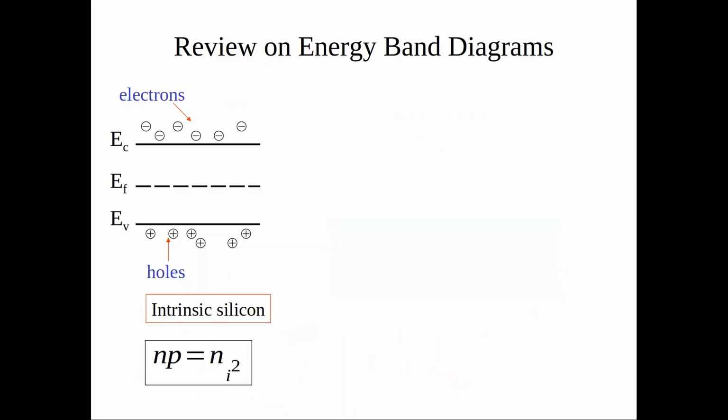If you just draw your band diagram, you can put the limit of the valence band, so you would have a lot of energy levels that go from EV down, and then the limit of the conduction band, and you have a lot of energy levels that are free from EC up. And then you have this gap between the valence and the conduction band. The one that would denote the equilibrium is the Fermi level. It's this EF.